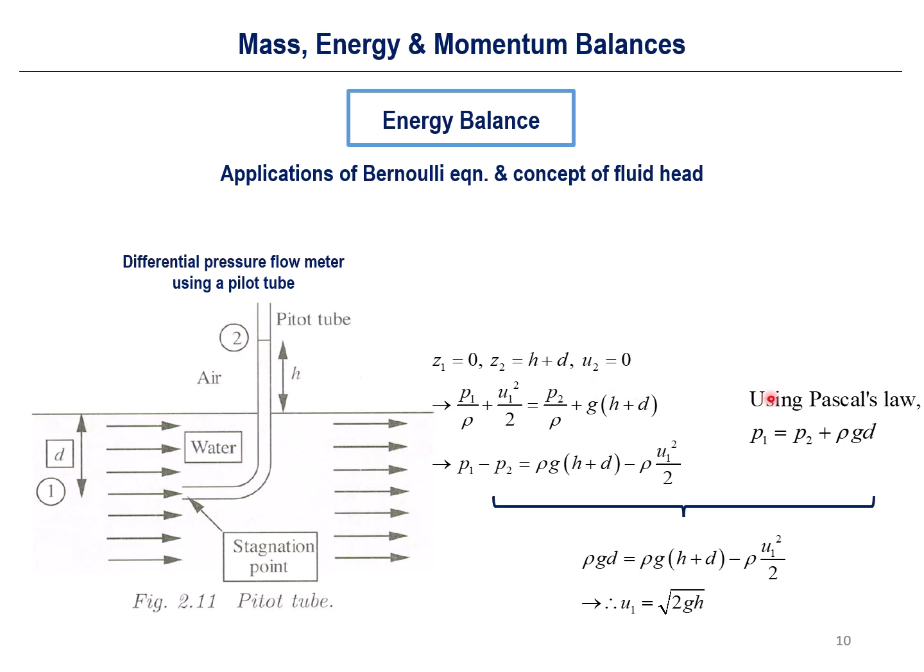And please also remember from your first week that Pascal's law can be applied to any type of continuous fluid. So your P1 is actually P2 plus the water mass-derived pressure, which is rho g d. Okay, so we have pressure differences, we have height differences. So now you can calculate by measuring this height in the P2 tube. And now you can finally calculate the U1 as a function of g and h.